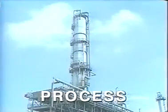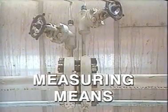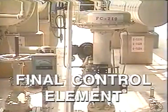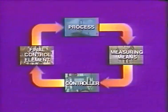First, there is a process that needs measurement and control. For each process variable that must be controlled, there is a measuring means, one or more instruments that can measure the process variable. There must be some kind of control mechanism to receive the measurement information and determine how it compares with the desired value or set of values. The control mechanism must also tell the valve what action, if any, the valve should take. And there is a final control element, which is usually a valve. The final control element makes the actual process change that keeps the process variable on target.